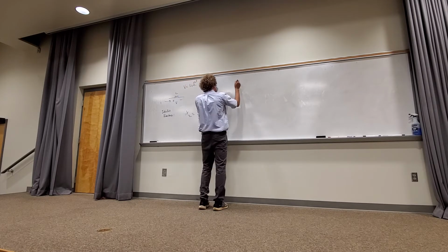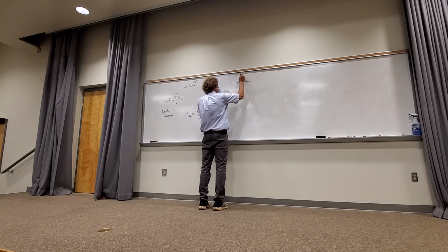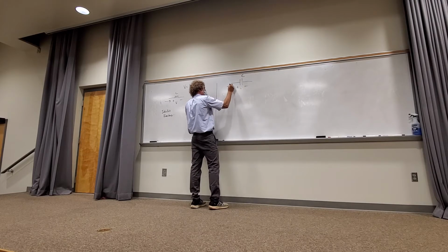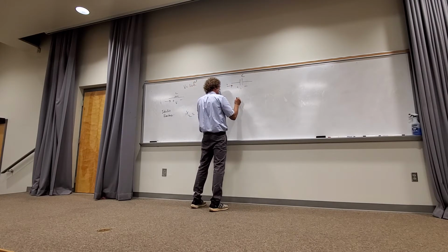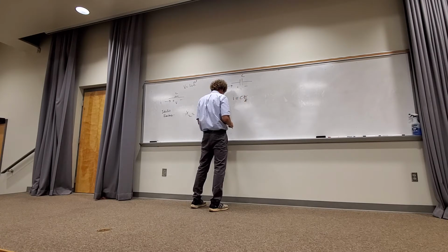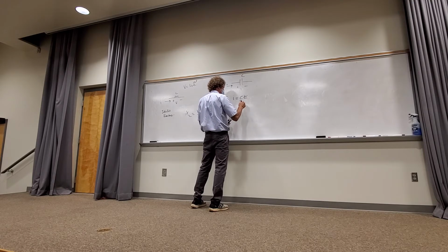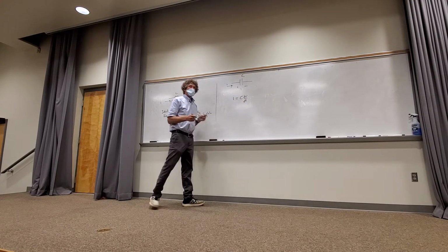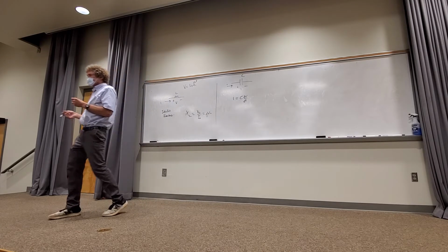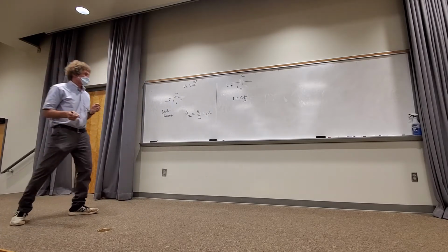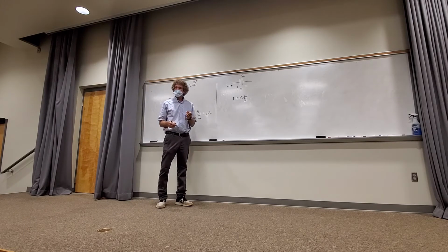This is for an inductor. If we have a capacitor here, we know it develops a voltage V for a current I, and we know C times dV/dt is equal to I. That means the time varying rate of change of the voltage across the capacitor is the current that's actually going to go right through that capacitor. That's the definition of the current-voltage relationship in a capacitor with a capacitance of constant value.